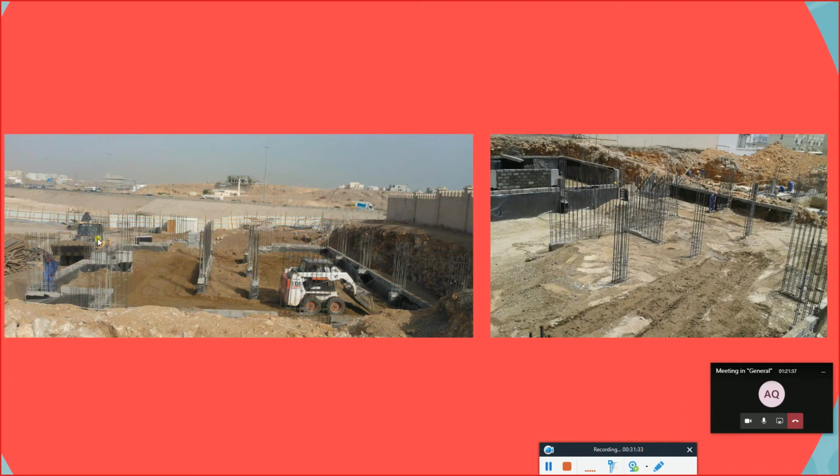Now, after we have done the bitumen layer, we have already done the excavation, built the foundation, and done all the steps. After that, we need to reach the ground level. So how do we reach the ground level? We need to have the backfill. We return the soil that we removed earlier as a backfill. Backfill means returning the fill which was there. Sometimes the soil is not good, so we need to bring soil from outside and then do the backfill.